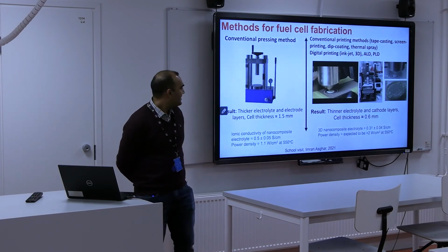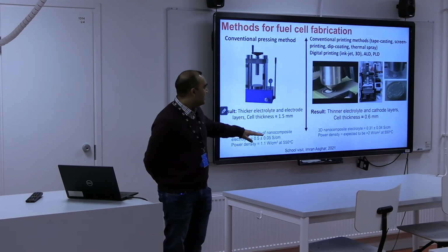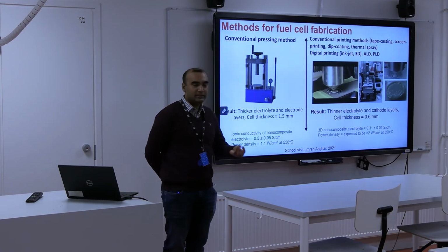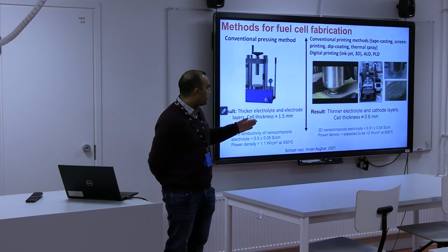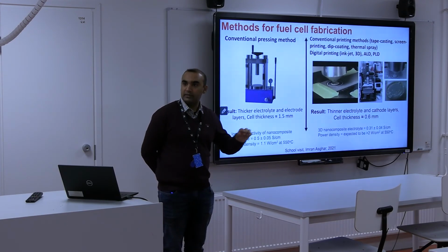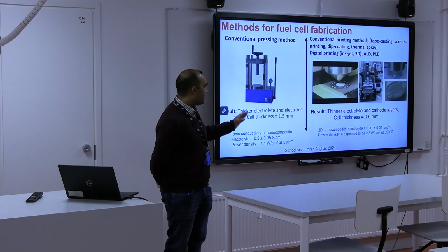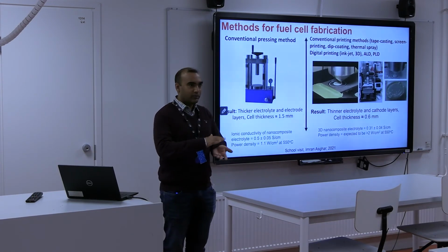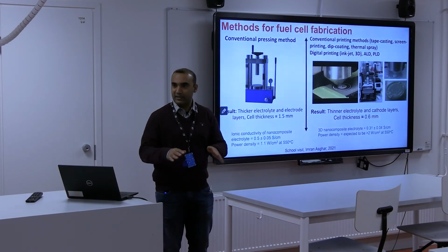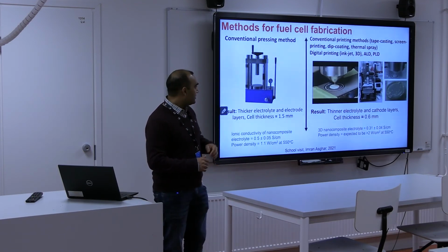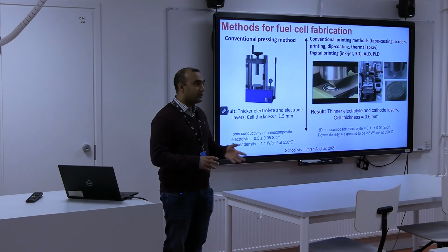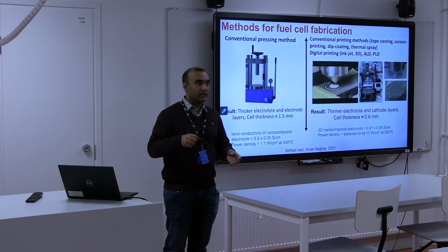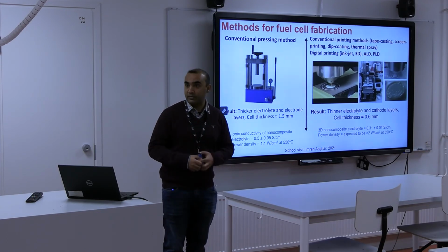Yes. So basically, these layers that we are forming, I think for this 3D printer, the nozzle size is much larger, but it's about a few microns, the thickness of those layers that we get from here. So typically, I think we are aiming about 20 micron, and then gradually we will optimize it. But at the moment, we try to make it a little bit thick, but thin enough that we get high performance. So that's one thing. And then we are also using inkjet printing, so we can make a skeleton with the 3D printer, and we can infiltrate materials because we need composite materials.